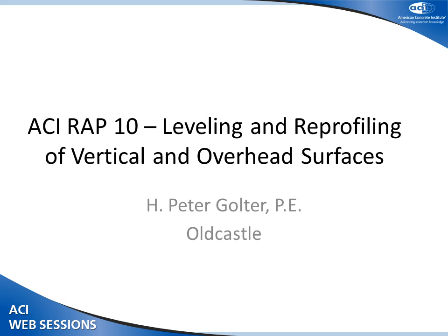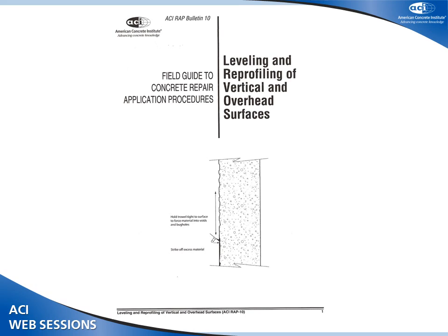We're looking at spalls, joints, cracks, and overlays as the solutions to those areas as we start looking at concrete repair. So far we've addressed cracks, both epoxy injection, as well as gravity feed. We've looked at several repair methods as far as how do I fix the visible damaged areas. And now we're going to talk about leveling and profiling vertical and overhead instances.